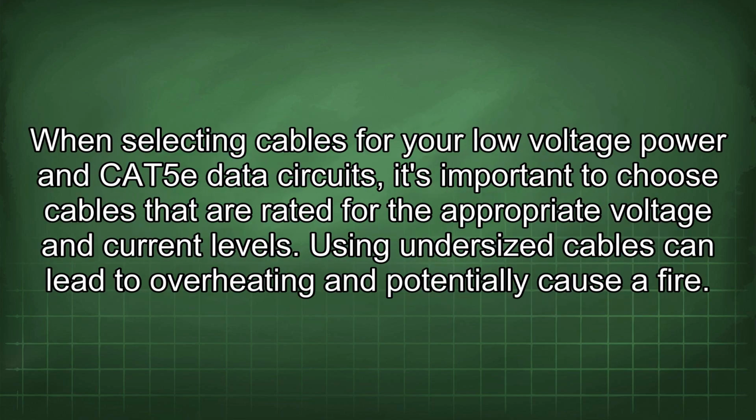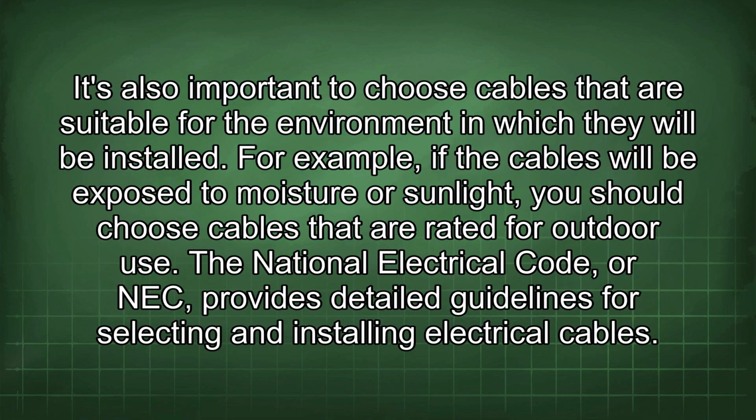When selecting cables for your low voltage power and CAT5e data circuits, it's important to choose cables that are rated for the appropriate voltage and current levels. Using undersized cables can lead to overheating and potentially cause a fire. It's also important to choose cables that are suitable for the environment in which they will be installed. For example, if the cables will be exposed to moisture or sunlight, you should choose cables that are rated for outdoor use.